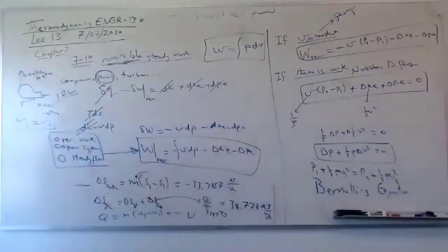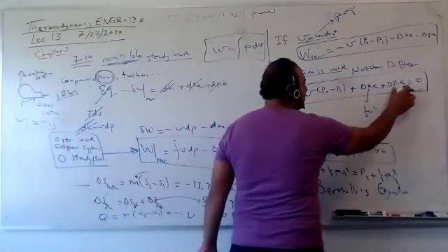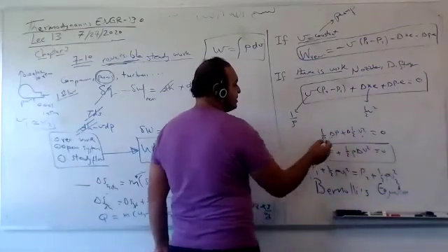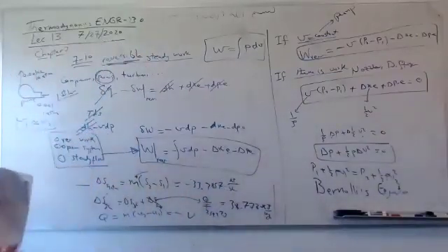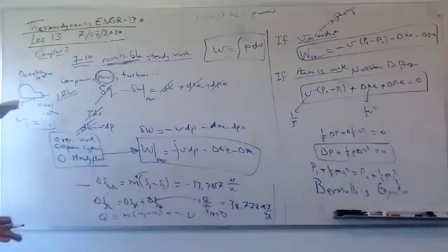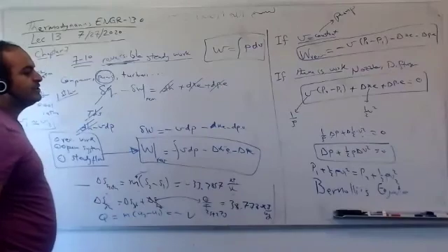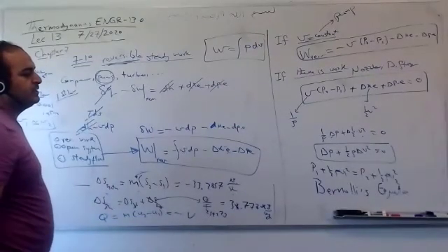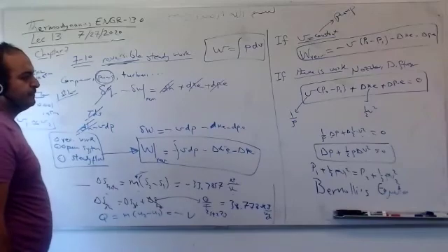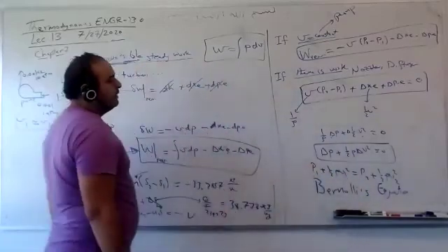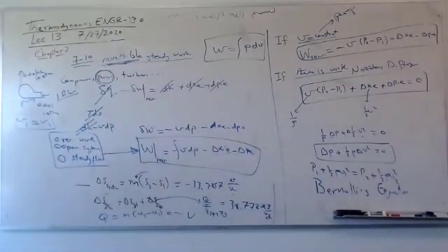Bernoulli's equation. The total energy is constant. This is like the free fall of a pen. This plus this equals constant. For flow over an airfoil, when the velocity increases, kinetic energy increases, pressure decreases, and so on. They are inversely proportional to each other. Pressure increases, velocity decreases. Pressure decreases, velocity or kinetic energy increases. This is Bernoulli's equation. How many have seen it many times? The total energy is constant. If we replace this and simplify it, it becomes a very famous form of Bernoulli. So it's no friction, incompressible.